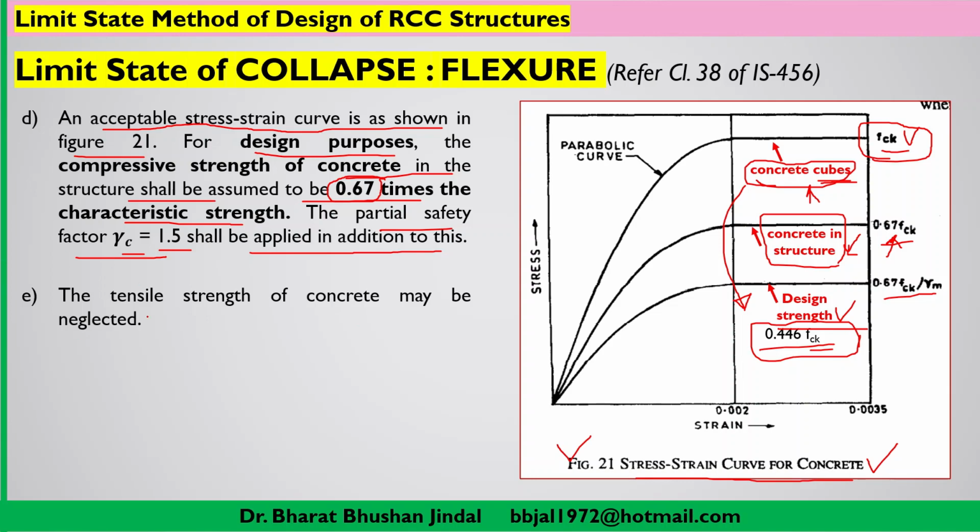The next assumption is that the tensile strength of concrete may be neglected. We have already discussed that when you are using concrete in an RCC structure, you are ignoring the tensile strength, whatever tensile strength the concrete has, you are neglecting it. And similarly, you are neglecting the compressive strength taking capacity of steel also. So for concrete, we are ignoring the tensile strength, and for steel, we are ignoring the compressive strength.